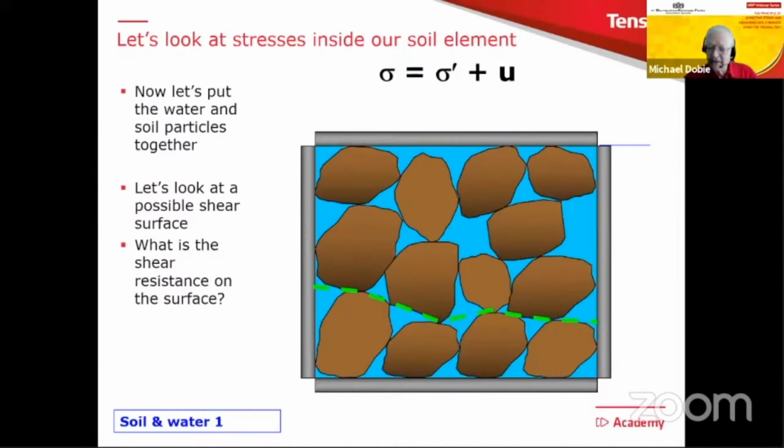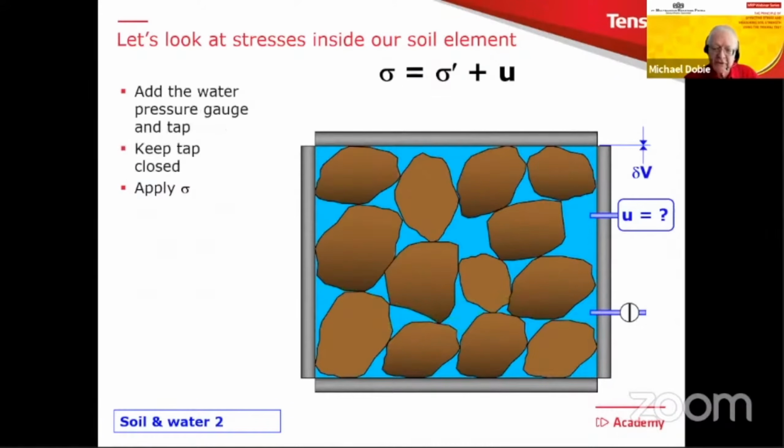We assume in this case that this is a tiny particle, and the weight of the soil grains is so small that you don't even notice it. So we're assuming that essentially there is no weight from the grains themselves, the soil grains. And of course, if that's the case, then the shear resistance must be 0, and that's because the effective stress is 0.